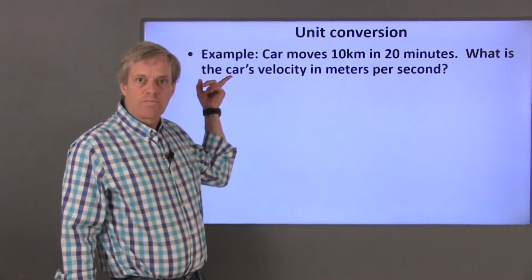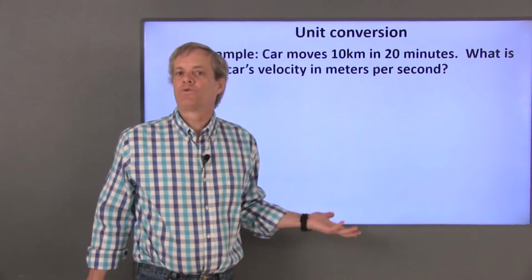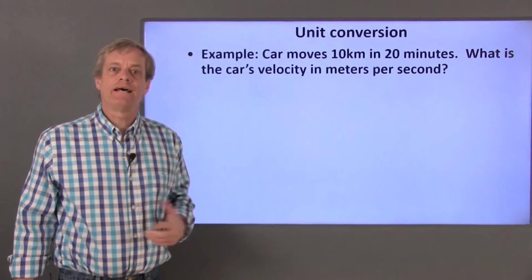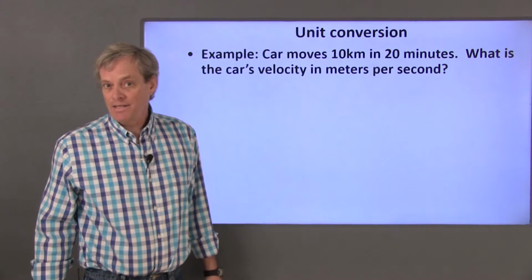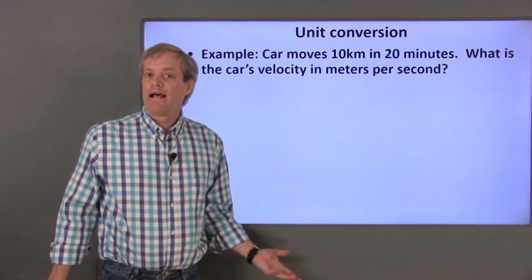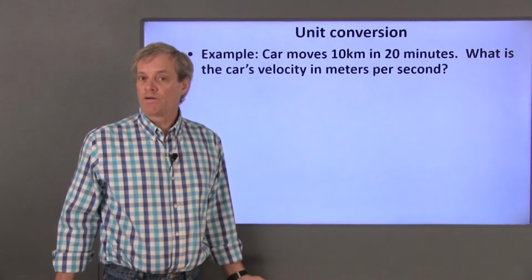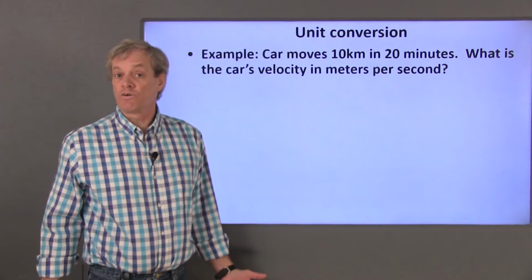Notice that when I was doing this problem, I didn't really worry too much about the actual approach, but no matter what I did, I kept track of the units on the individual terms and made sure that the dimensional analysis turned out correctly. If the dimensional analysis works, I can be pretty sure that the numerical values I'm multiplying and dividing by are correct. Mathematicians' numbers can be abstract, but engineers' numbers need to include units in order to give the numbers meaning. Indicating units and following dimensional analysis can also save you from some silly errors. If the units don't work out, the calculation itself is probably wrong.